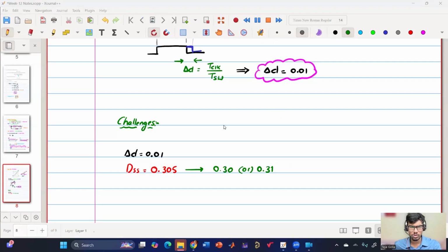So this is 0.30. If you see from the control perspective, say buck converter, if I have the duty ratio less than the required duty ratio, my output voltage is lesser than the required voltage. So the error is positive, so the control voltage will increase. If my duty ratio is again above the required one, then my output voltage is above the reference, error is negative, so it will try to decrease. Until and unless I reach the point, either I am below or I am above, but not at that point. So what is going to happen? What do you think is going to happen?